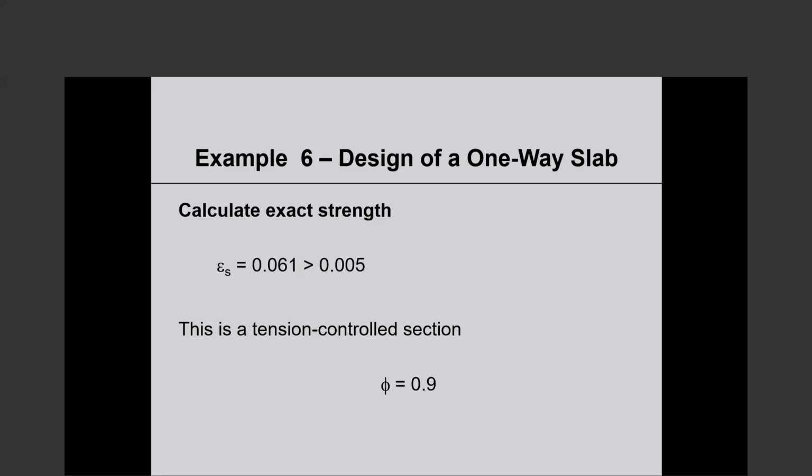Sometimes I do not quite understand the thinking. If you have a slab integral with your beam, the slab is part of the beam. And the fact that the slab is part of the beam does not depend on whether you have some perceived deficiency or not. Read the question again.